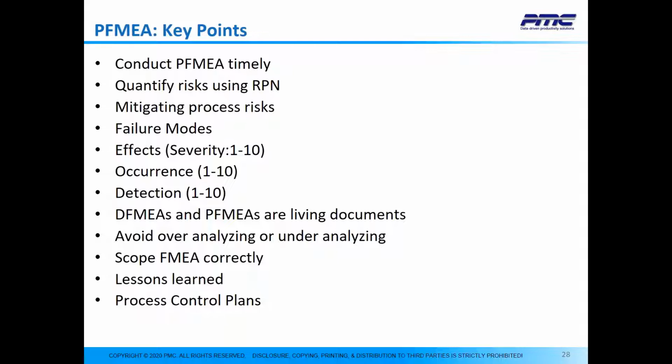Because if we tend to do that, that defeats the purpose of overall APQP's goal, because APQP methodology begins with the design record and design risk assessment. And the design FMEA is done to identify those risks and mitigate them during phase 2 of APQP. When you're in phase 3, where you're developing the process, again, you're assuming that the product will meet its intended requirements, because otherwise it will take forever to complete the process.